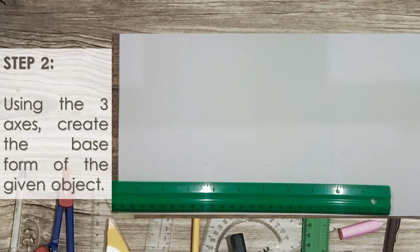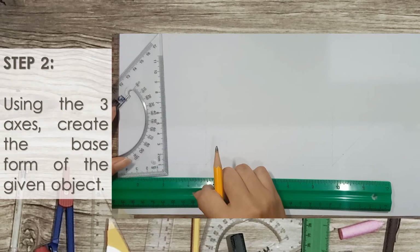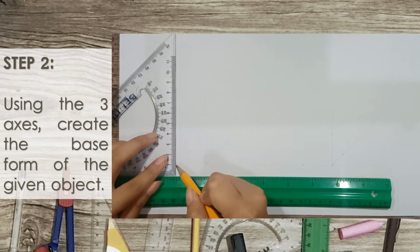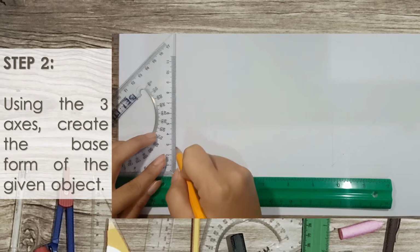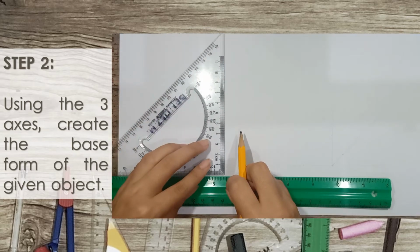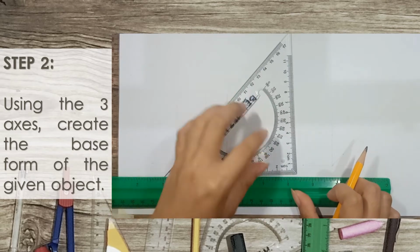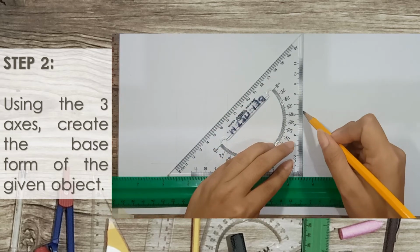For step number 2, using the 3 axes, create the base form of the given object. So when we say base form, it is the origin shape of the object that we are going to create. So we just have to project from the points that we have created. So in our cavalier drawing, we will be projecting this line. Okay, so let's just create or project all the vertical lines. And in a cabinet drawing, project.